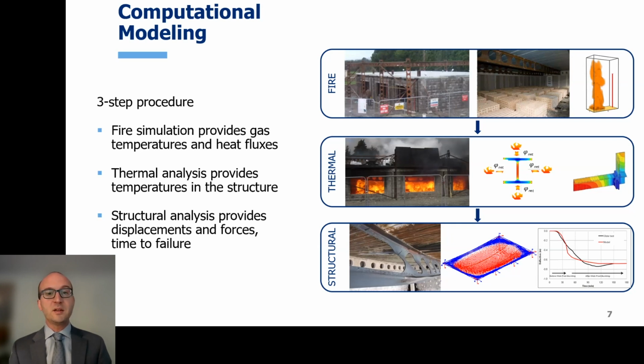Second, we need a thermal analysis, a heat transfer analysis, that will compute the temperature increase inside the members based on the fire exposure, of course. And third, we have a structural analysis where now we check deformations and forces in the structure, considering the temperature increase.